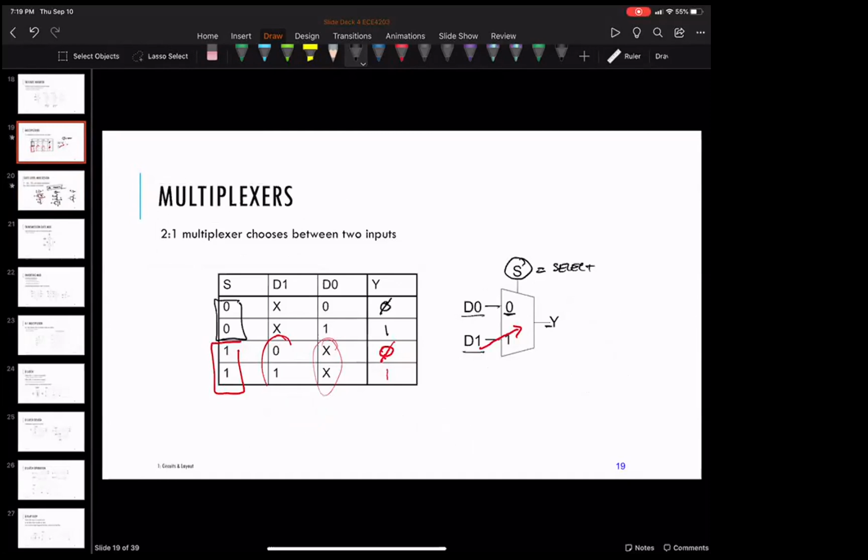What you could do is make a really simple multiplexer. So instead of 20 transistors, you could make a 2 transistor multiplexer, if NMOS was that perfect switch. So what you would do is you'd put 1 NMOS.